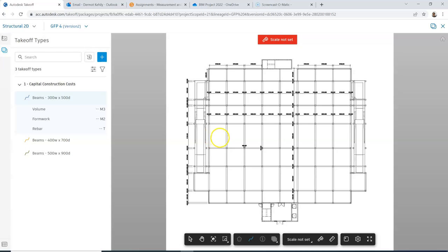And obviously the top floor where the beams are, that's in the roof, but leave it in the structure. So we're not defining whether it's roof or whether it's floor construction as such from a frame point of view. You're just measuring the beams. Don't worry about the columns. And the other item you're to measure is the gross floor area per the project brief, and you should have no problems. I've set you up there to measure all the beams in terms of your concrete, your formwork, and your rebar. If there's anything else you want to measure, by all means, work away from a 2D perspective. But all you need to do from kind of an assessment perspective is measure your beams in the 2D. So hopefully it won't take you more than a couple of hours maybe to do that, or even less.